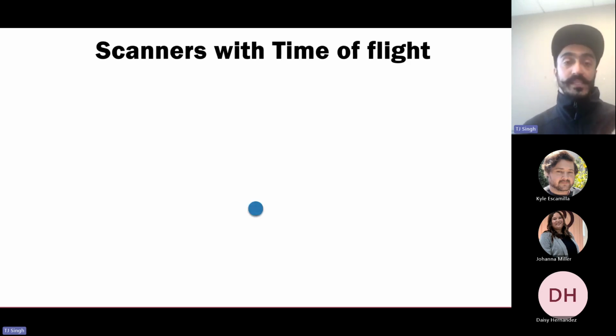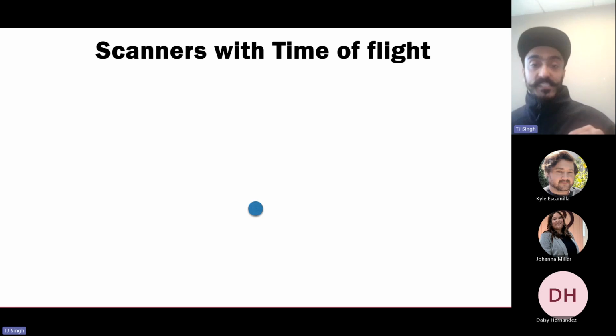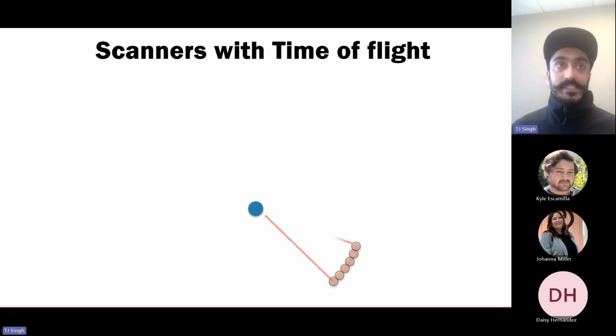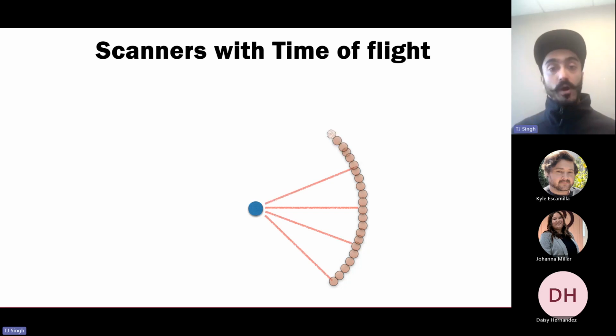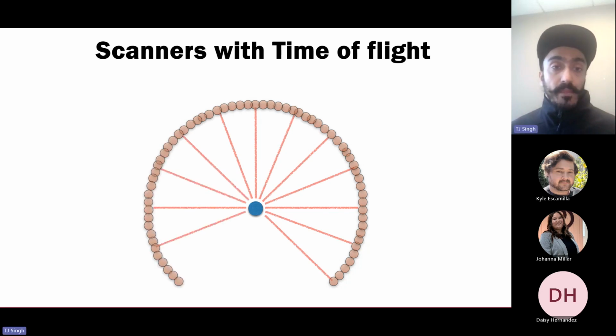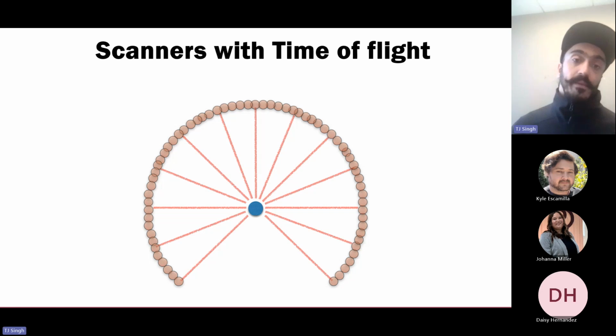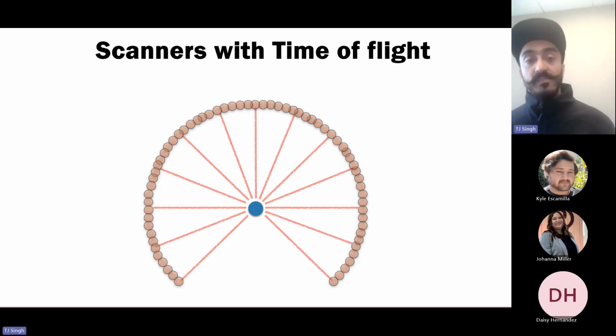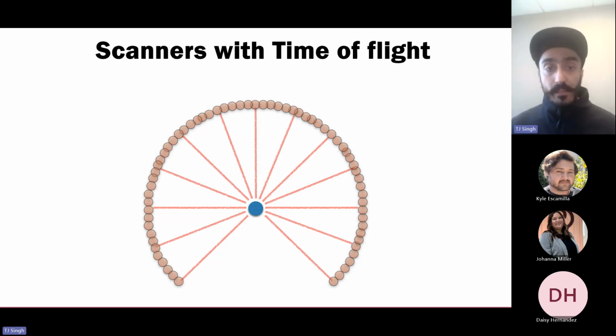Now, what happens if you put this technology on a structure that is spinning on its axis? Then essentially you're able to grab a whole lot of data points on a 2D plane. And if you see this small animation, you will understand. We are creating this entire data mapping in a way where we are getting everything back. And hence we are able to know whenever anybody comes into this environment, and we can trigger a safety stop based on that. That's how LiDARs work, and that's the core principle of the nanoScan3 as well.